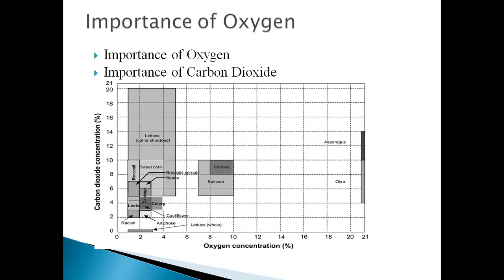Moreover, high levels of the gas are unhealthy and can lead to occupational hazards. The effects of very high concentrations of carbon dioxide can range from headaches to unconsciousness and even death. Therefore, levels should be monitored with the utmost care in storage and ripening rooms. The standard carbon dioxide level in the air is 0.04% by volume.